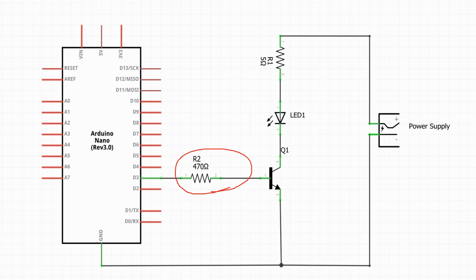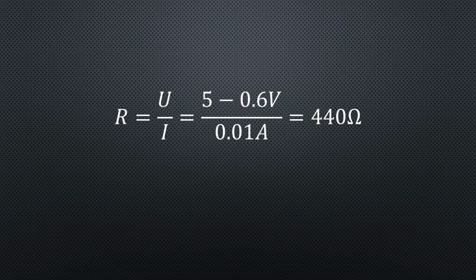The diode from base to emitter has a voltage of around 0.6 volts. And the transistor amplifies the current by a factor of 50. Our LED will use less than 0.5 ampere. So the base current will be around 10 milliampere. Okay, even for an ESP. The resistor is then (5 - 0.6) / 0.01 = 440 ohms. The standard value 470 is okay too.